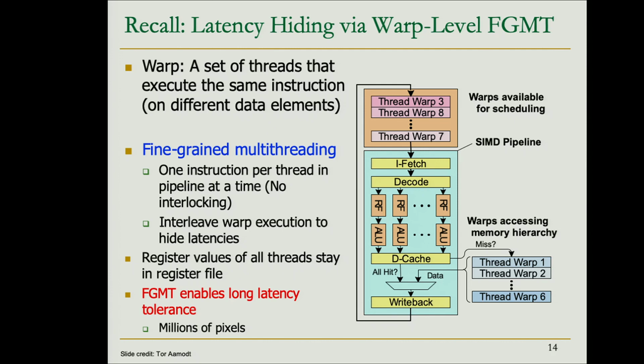So we decode it, and then we have these scalar pipelines in parallel, and each of them represents one of the SIMD lanes inside the GPU core. We need to read from the register file the operands of the arithmetic operation, for example, that we're going to execute.